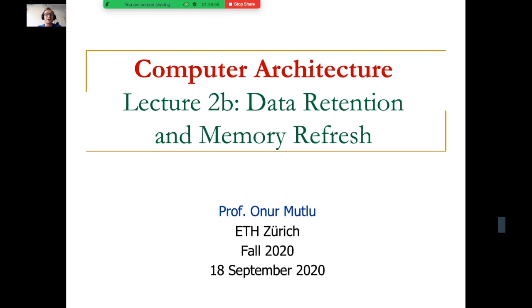And again, it's very hardware-software cooperative. You cannot do this without knowledge of what's going on at the higher levels of the software: how you're accessing data, what your access patterns are, what is important and what is not important in terms of access and computation, what you should prioritize, what you should not prioritize. If you have all of that information, and if you can communicate that to the memory controller, then the memory controller can also be reprogrammed or reconfigured to actually implement a policy that satisfies the needs at the higher levels of the software. And that's what we were mentioning yesterday when we talked about cross-layer design. This is an example of cross-layer design that's really waiting to be done. There's some research toward that direction, but no research has shown end-to-end that this works really nicely. So there are opportunities here. And the interfaces I discussed yesterday, the expressive memory interface for example, is one interface through which this information can be communicated, but maybe you need something else to be able to do that as well.